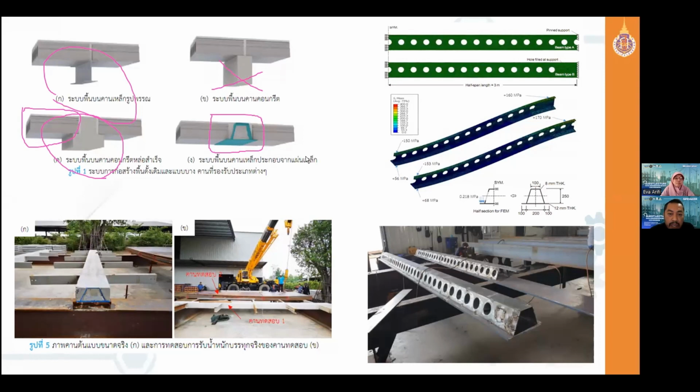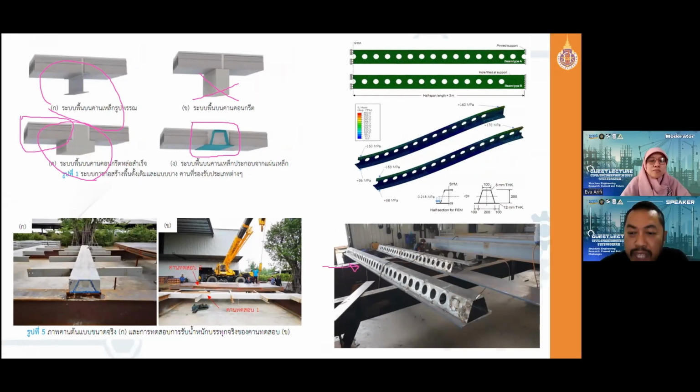And yeah, we got a really good company to supply us with the testing beams like this. So we did the testing. Remember, this is full scale, 6 meters long, and I also do some structural computer optimization to select the thickness, the length, the height, according to the required live load.